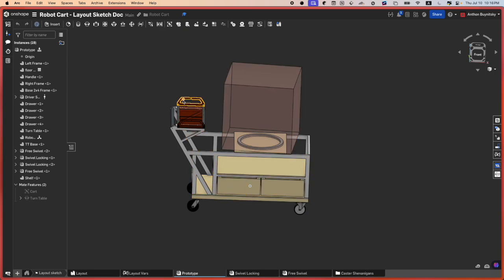Before you layout sketch, what you actually want to do is draw out any ideas for robots that you have. Going straight into layout sketching before having anything drawn out on a piece of paper is very hard, because sketches in Onshape don't act like a whiteboard or pen and paper. You have to think about where to place the lines and assign dimensions. It doesn't have as much freedom as a pen and a piece of paper.